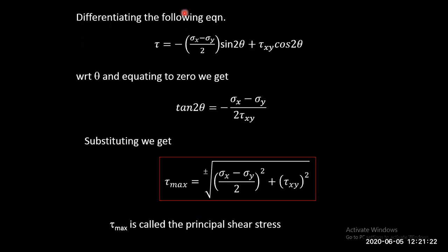And this is also how you get the values for shear stress. Again, you have the shear stress in a biaxial stress system with shear, and differentiating that with respect to theta and equating it to 0, you'll get this equation. So that's the principal shear stress.